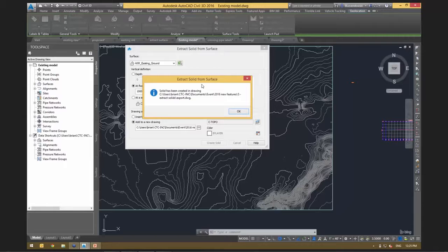A side note to that, I see a lot of problems with migrating templates after a number of years have gone by. A few years seem to be okay. If you've been migrating a template for 7, 8 years, I start to see problems. And when you do that, you have to rebuild the template. I don't mean recreate all the styles from scratch.